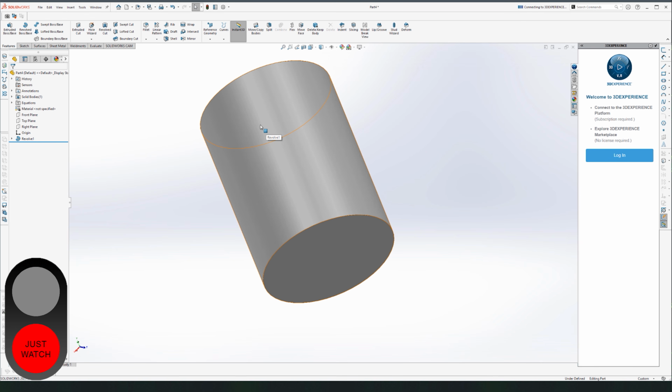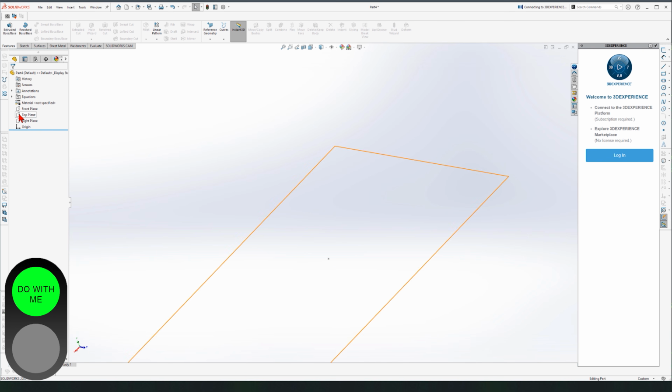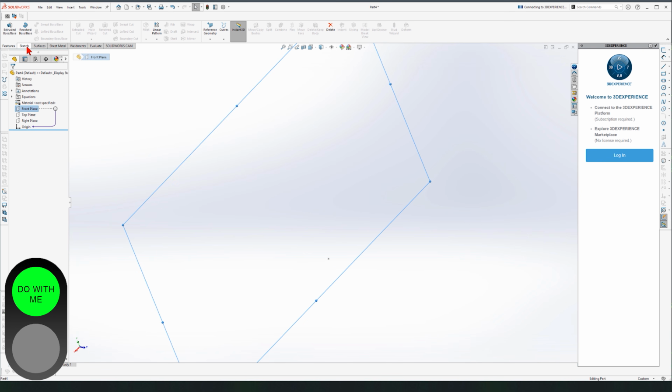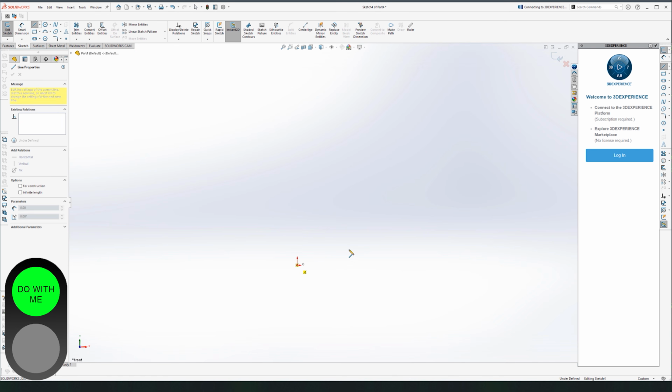So I want you this time to go to your SolidWorks and follow my steps at this next green line from here. Looking at an empty canvas. Select front plane. Go to Sketch tab. Click Sketch. Line. Draw these. Horizontal. Make sure you're not going here. You're not going here.